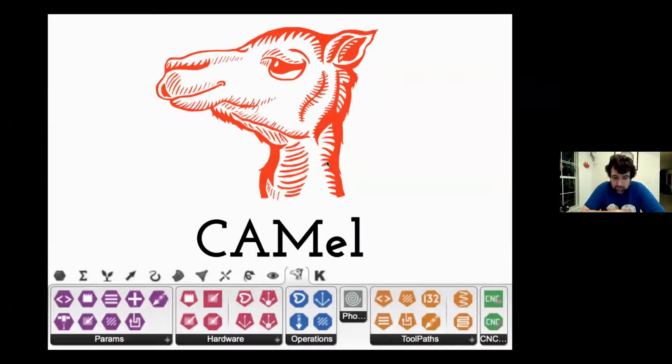And the problem when I wanted to go beyond that to deal with 3-dimensional systems was that it was not easy in the standard tools you use to control CNC machines to just do an arbitrary path, to just make all sorts of 3-dimensional curves and tell the machine to carve along that. The software was always set up for you to give it the object you wanted to have coming out, and then it would create the paths that would generate that object. And that wasn't what I wanted at all. I wanted to be able to draw the paths and have the machine carve them.